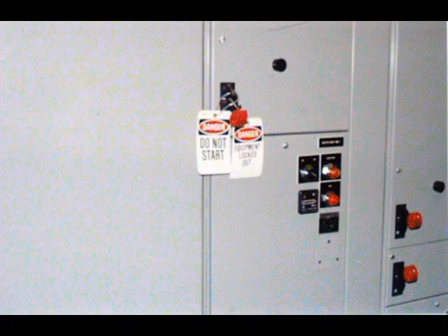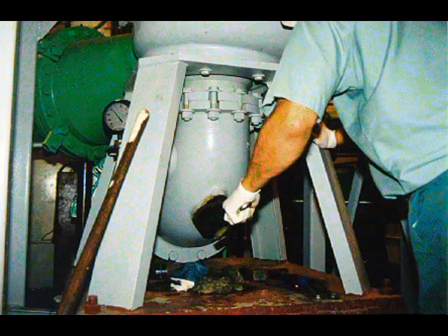The first thing to do when unclogging a pump is to tag out and lock the motor in the off position at the electrical panel. If the valves are motorized, a lockout-tagout procedure is also recommended for the valves. Drain the pump and then remove the cleanout hole cover to remove the debris. After the cover is replaced, be sure to prime the pump before it is restarted.